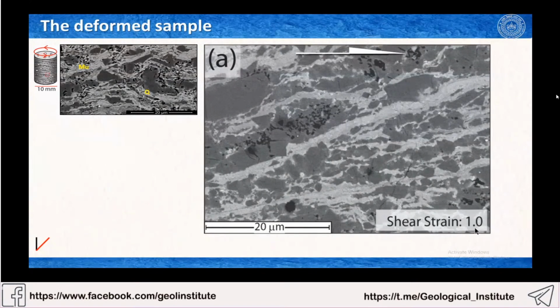So in this case, this is shear strain 1. We more or less see the same scale of these two, initial microstructure and deformed microstructure, so that you can compare how it is deviating from the initial to the stage we will be looking at. These little white, black and red lines would indicate the magnitude of strain. So this is the vertical, and this is now 45 degrees, defining that it is shear strain 1. And with more shear strain, we will see that these red lines would slip more.